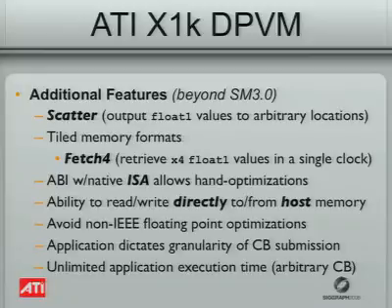You also have the ability to read and write directly to and from host memory without an additional copy. So the PCI Express does the transaction directly to system host memory. And you can also avoid non-IEEE floating point optimizations. So NaNs and infs can actually be given the correct behavior using this abstraction layer, since you do have direct device interaction.